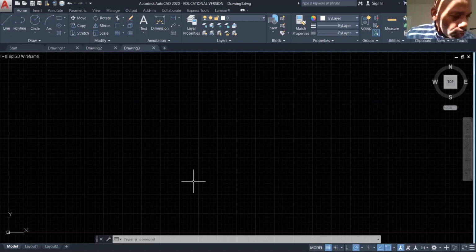To do that, I want you to make reference to the layer properties PDF that you printed out, okay? We see that we're going to be creating these. How many layers? There's 1, 2, 3, 4, 5, 6 layers, okay? We're going to be creating a title block layer that has a magenta color and a certain line type, okay? Object layer, hidden layer, center lines, and text, and a non-plot layer. Okay, we're going to do that.